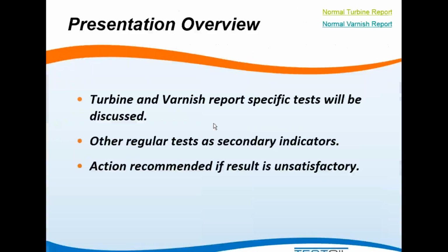We'll be going over the turbine and varnish reports today. Since we have a limited amount of time, I'm not really going to talk too much about the standard tests like spectroscopy and viscosity. We want to focus on the tests that we only see on varnish reports and turbine reports. But we will take a look at that if there's additional information that we can glean from perhaps a report that's an alarm and see if any of the other tests tell us something different.